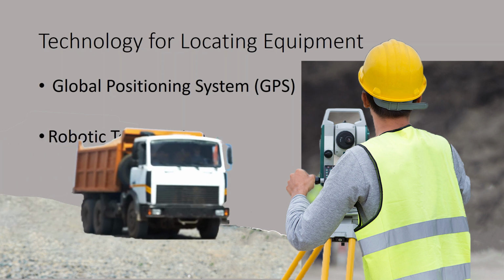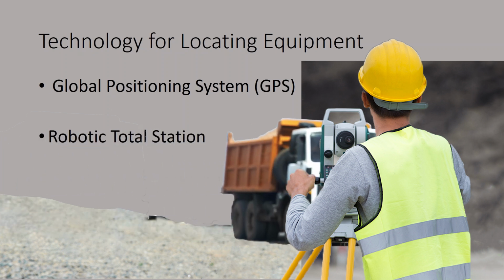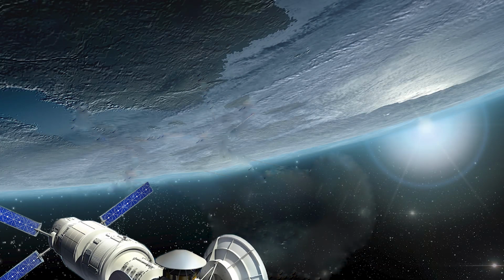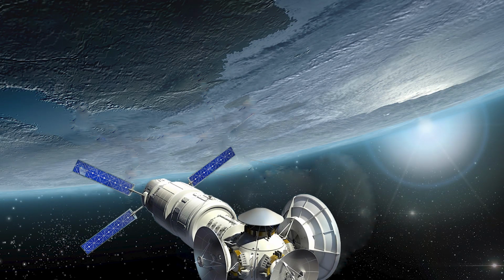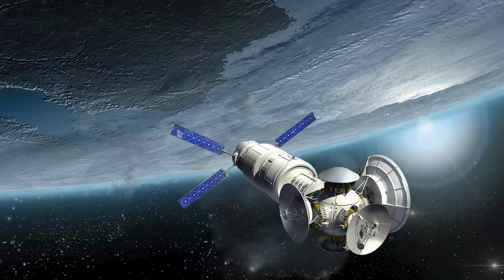And so if a truck pulls in between there, it'll actually give a signal to the driver of the motor grader or whatever that, hey, we're not getting signal anymore. And so depending on what stage they're at, if they're still hogging out material, got to go another 3 foot, they'll just keep going. They'll pick up the signal when they get line of sight again. If they're actually doing the final finish elevation of that roadway, they'll probably stop, yell at the truck driver, then continue on. The GPS, that one, you're looking for GPS satellites.